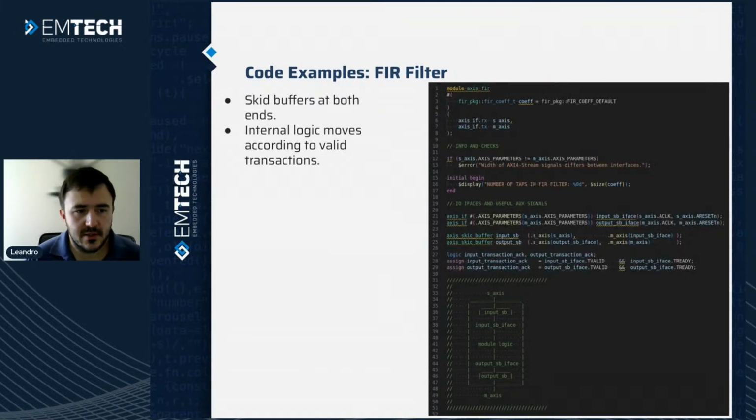So using this interface, I wrote as an example a filter. I wanted to actually mention this one for its very short list of ports, because you will see that I only have lines 6 and 7. This is the input and the output, and the clock is actually included there. There's no way to tell that the clock is the same in both interfaces. That's maybe a limitation of the SystemVerilog interface implementation, but I'm giving as a parameter a data type with the coefficients.